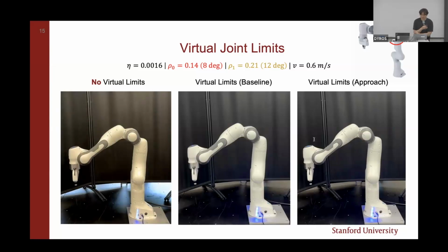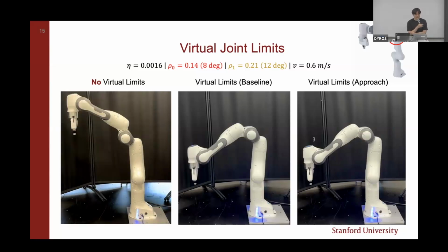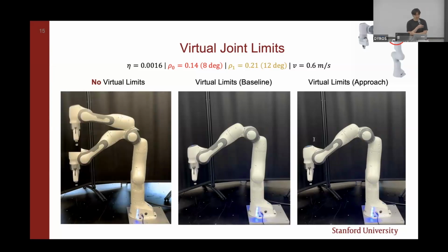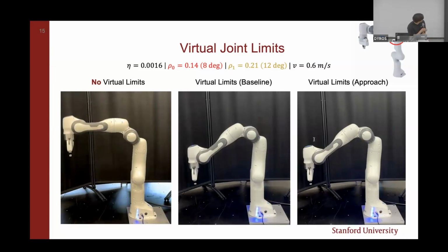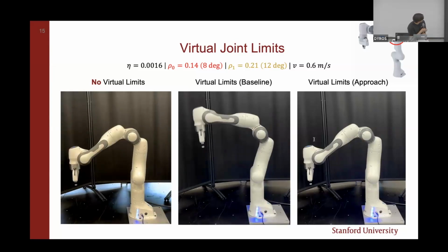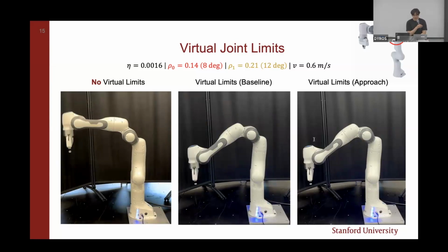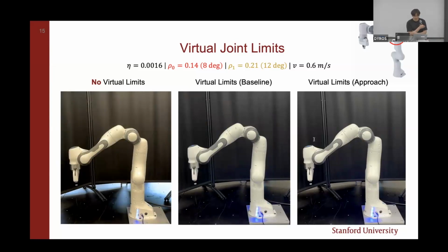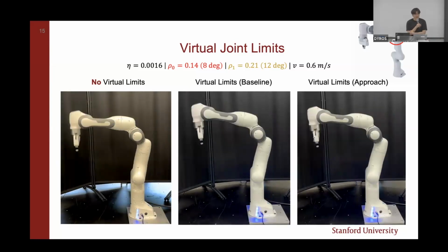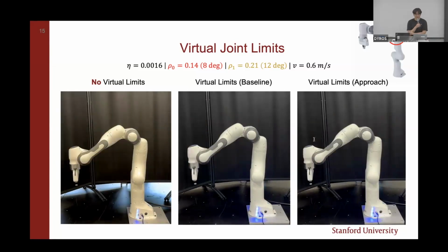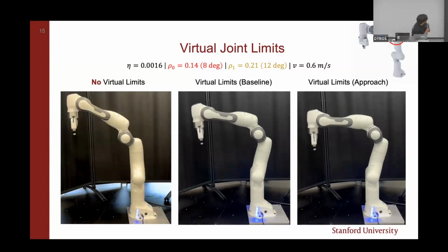In the second video, the baseline implementation results in oscillations due to the high entry joint momentum with the APF field parameters. And in the third video, the approach is shown where the joint experiences no oscillations approaching the virtual joint limit and smoothly exits the joint constraint zone influence using the control task.